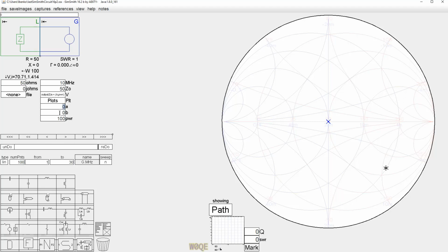We set its output impedance. We can say its output impedance is, say, 50 minus J20. So if I build a transmitter that was supposed to be a 100-watt transmitter, supposed to drive 50 ohms, but my output impedance was really this, I could use this as the model. And as I move the load around, this will no longer be the maximum power point. The maximum power point will occur when this is 50 plus J20, which would be the complex conjugate of that impedance, and it's 104 watts there. But it's pretty close.